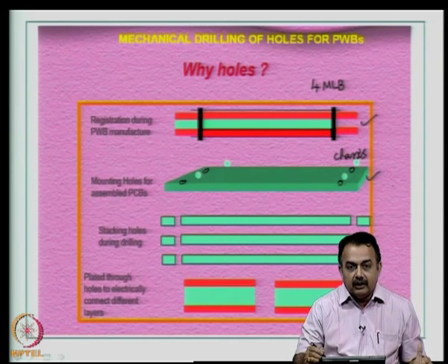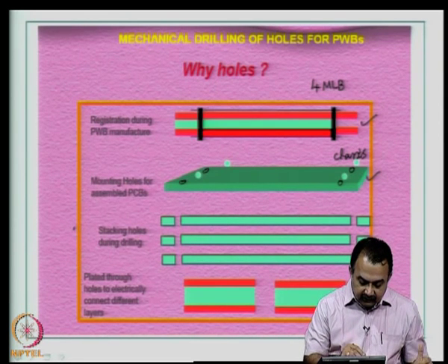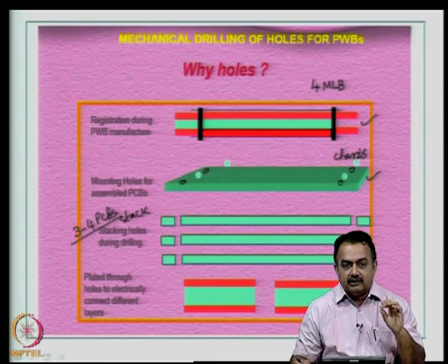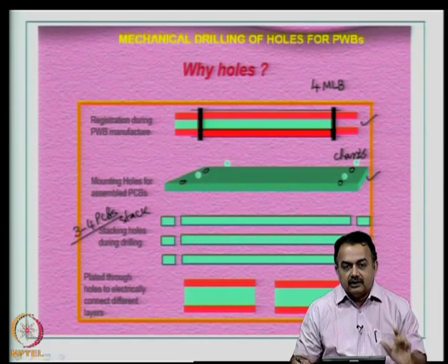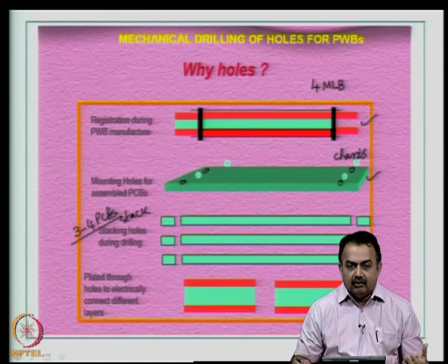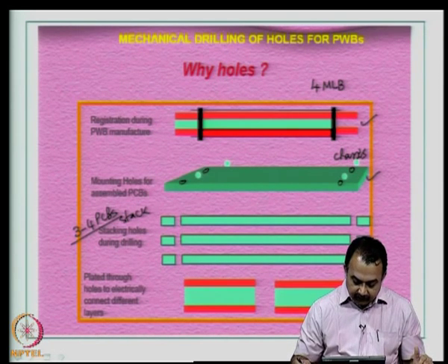Stacking holes during drilling: even during the drilling step, when you are stacking, let us say 3 to 4 PCBs at a time, you require all the laminate structures to be stacked perfectly, so that there is no misregistration or vibration or movement during the drilling process, because if that happens, you are going to break the drill bit, you are going to get a misregistration and you will end up with a wasted laminate structure.